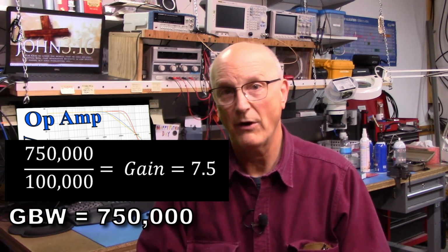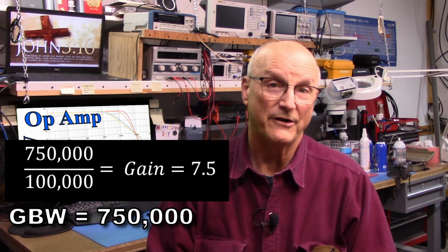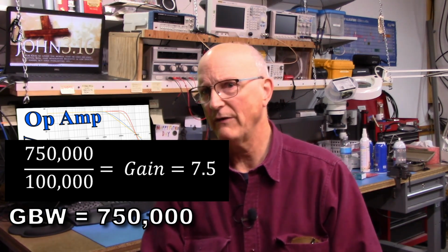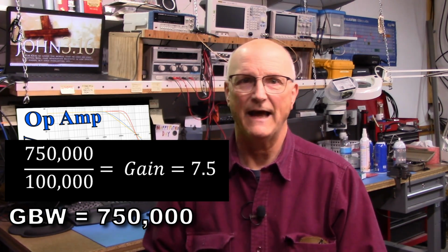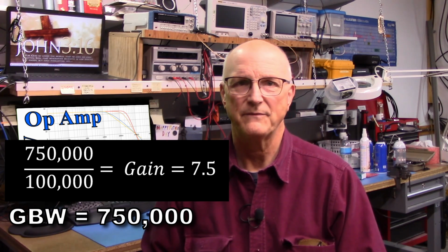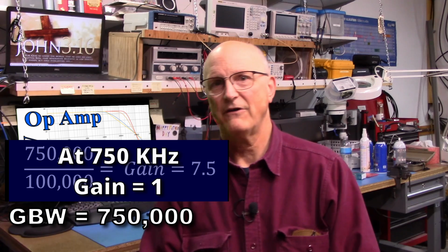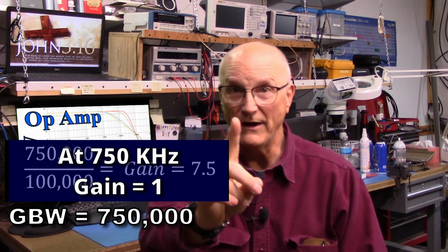So we have 750,000, the gain bandwidth product, divided by 100,000, the operating frequency, which gives us a gain of 7.5. So at 100 kilohertz, the gain of our amplifier has dropped from the programmed value of 50 down to 7.5. At 750 kilohertz, the gain of our amplifier will drop to 1.